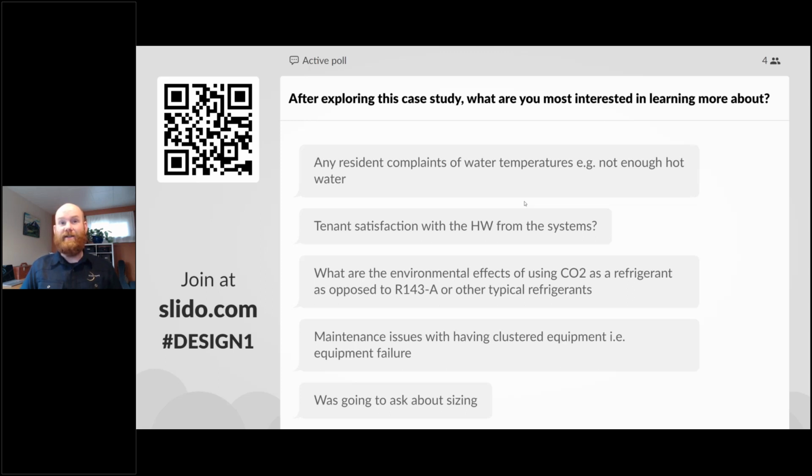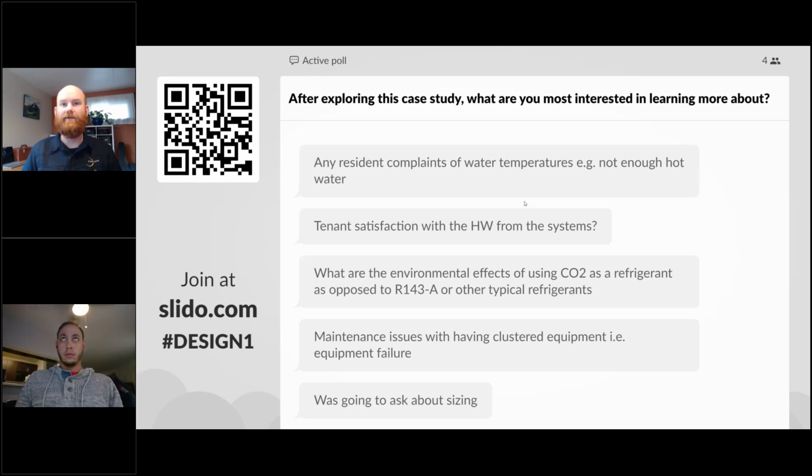The Sanden actually makes 150-degree water, and that is stored in the storage tank, which allows us to use that thermal battery more effectively because we have more thermal energy in that tank. But it does mean that we need to mix that water down. So we take the cold water and that heated water at 150, and mix those together to always target 120 degrees Fahrenheit out to those tenants. And that's one of our common design solutions using heat pump water heater technology.